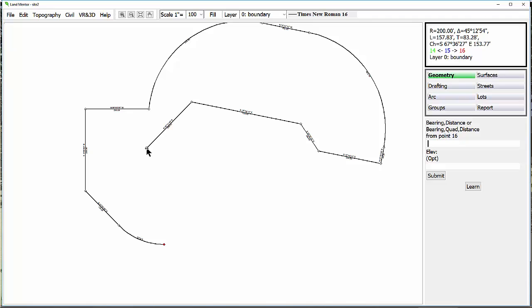If I had a compound arc, because again it sets a tangent, I could do something like this. And that would be, I'm going to say arc to the left, 78 degrees, 32 minutes, R, 90. Now notice I switched the two. Before I had the radius first, and now I have an arc to the left. The delta is first. It doesn't matter in the order.